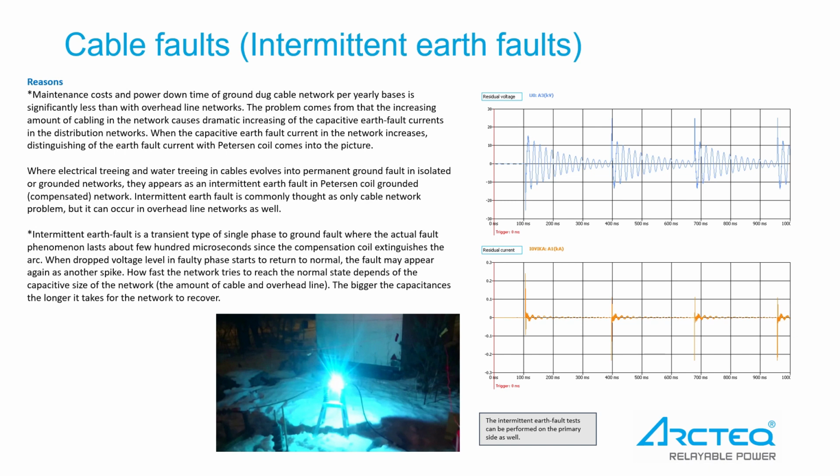The strike-through time of an intermittent earth fault in closed resonance-tuned network sets the limit for the minimum operate time of an intermittent earth fault protection stage. To ensure a correct protection operation in all cases, the reset time of an intermittent earth fault stage shall be set according to the network in question. The size of the network is a dominant factor in defining the strike-through time interval.